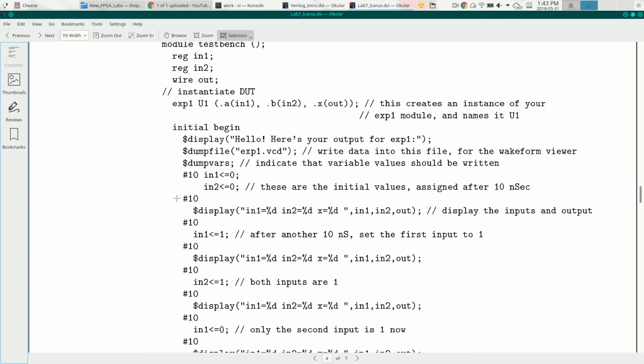Or maybe you're worried about timing. Maybe you want to make sure that this circuit can run as fast as possible. Or maybe you want it to take the least power possible. Or maybe you want to minimize the difference between the longest propagation delay and the shortest propagation delay from input to output. These are all knob settings you can set on the fancier software. And this is where your compile step can go from a few seconds to 3 or 4 days.